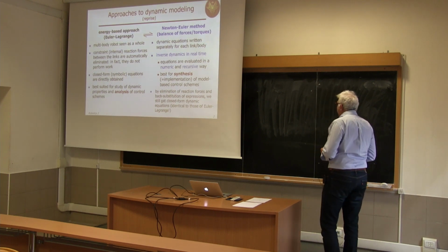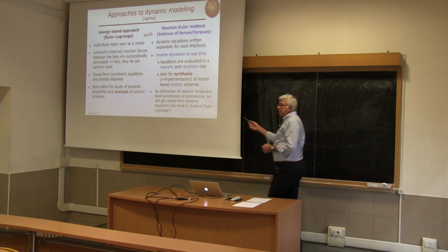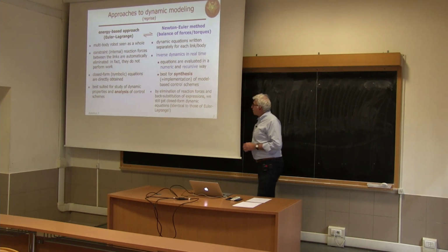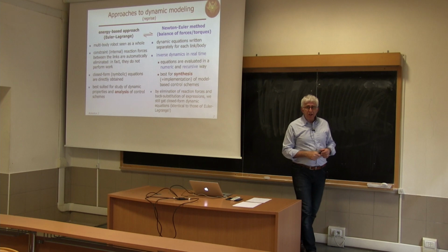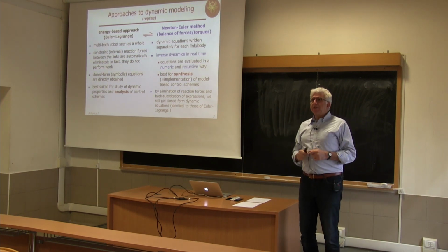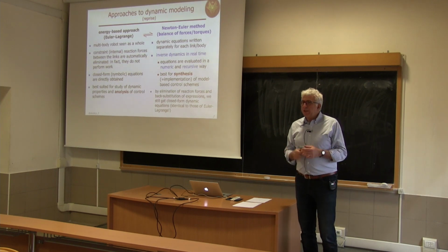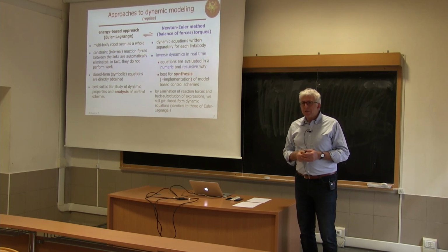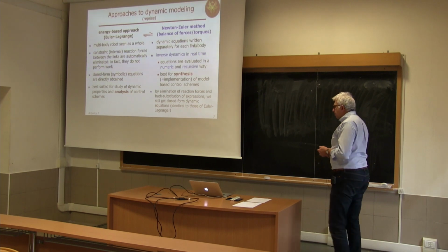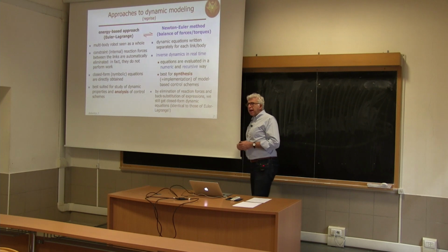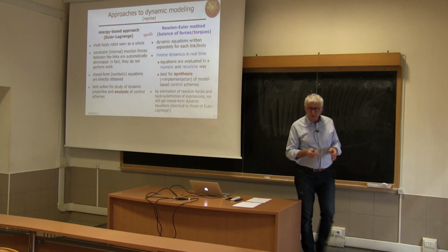But this is really very boring to be done because those equations are best for numerical evaluation. So instead of replacing symbolic terms from one equation to the other, we just plug in the numbers depending on what we need to do. For instance, the most classical situation is using the Newton-Euler method for inverse dynamic computation. In that case, we assume that a desired trajectory is given, and we would like to compute the torque that produced that motion.